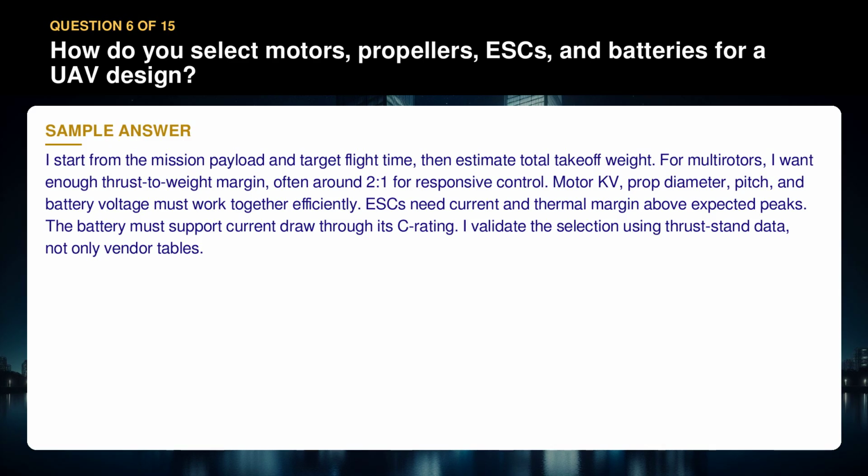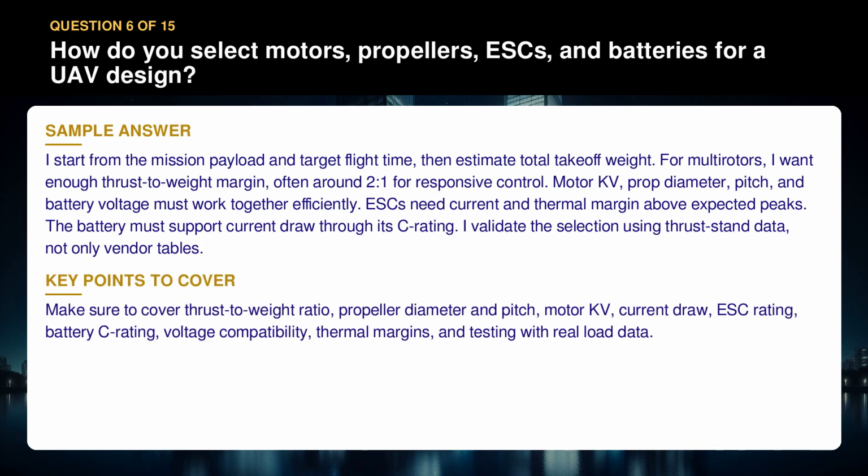I validate the selection using thrust stand data, not only vendor tables. Make sure to cover thrust-to-weight ratio, propeller diameter and pitch, motor kV, current draw, ESC rating, battery C rating, voltage compatibility, thermal margins, and testing with real load data.